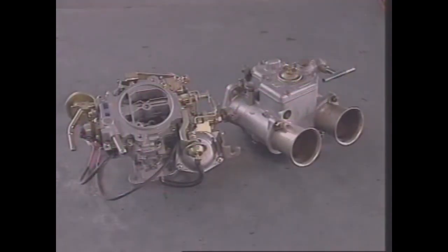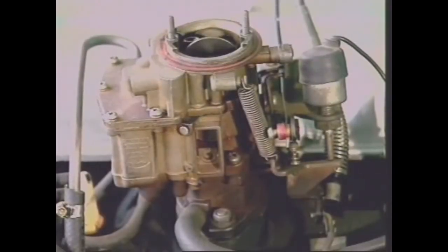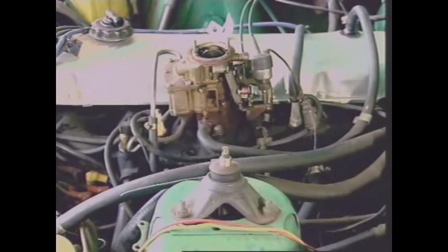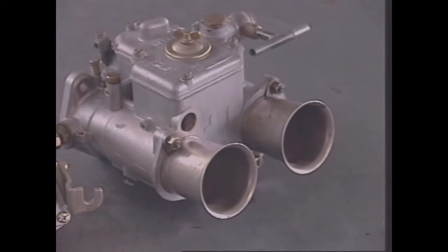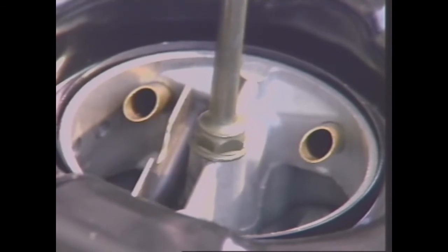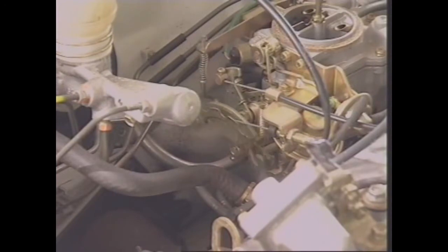The carburetor has to supply the correct mixture of air and fuel to suit all operating conditions. The downdraft carburetor is the most common kind. It's mounted on the intake manifold. The side draft model is less common. The carburetor turns liquid fuel into a fine spray and mixes it with air. It also controls how much air-fuel mixture is delivered to the engine. This is done by the throttle valve near the bottom of the carburetor, which is connected to the accelerator pedal.